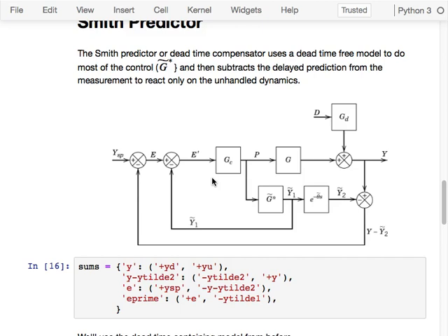So these two techniques are the only two techniques that we'll do in the entirety of the course that allow us to accommodate easily, or incorporate easily, the effect of nonlinear process models. So if we have one, the Smith compensator and the steady state feed forward are the only techniques that you know right now that could possibly benefit from having a nonlinear model. All the other systems, we require that you linearize that model up front. So, very, very cool. Okay?